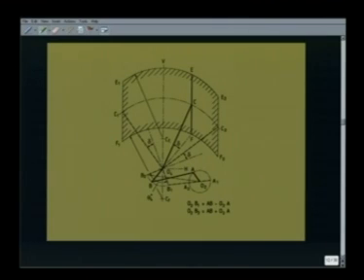To determine the wiping field, we see that because it is a parallelogram linkage, the point C goes in a circle with O4 as center and O4C as radius. Because it is a parallelogram linkage, all the points of the coupler move in identical curves. That means the curve generated by the points E or F, that is the end of the wiper blade, also will be similar circles, exactly of the same radius as O4C. Only the center of the circle will be shifted from O4 to CE for the point E, and O4 to CF for the point F. That is, CE-CF is the same as